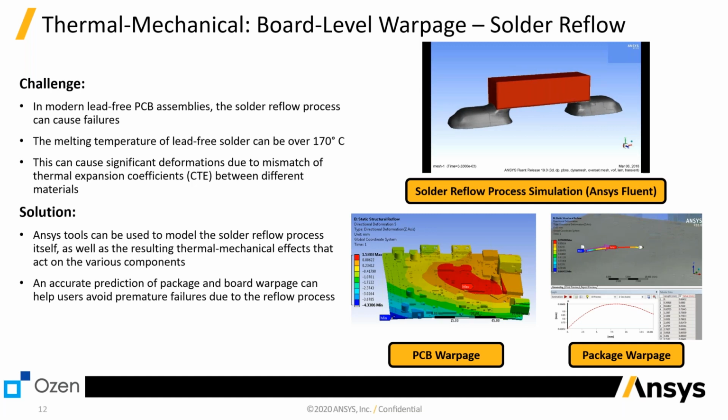And talking about the board level warpage, we do have the means to do the solder reflow simulation. Why is the solder reflow important? Because as you see here at the beginning, the solder started out as a rectangular block, but during the reflow, it's going to melt and it's going to take a certain shape.